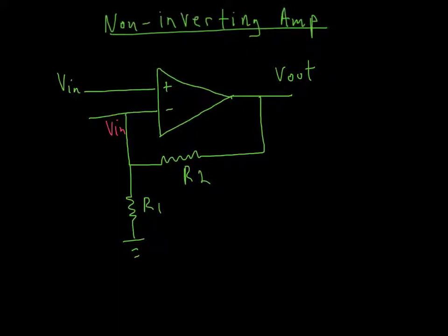Okay, and remember the op amp, golden rule number 2, the op amp draws no current. So if there's no current going into here, there's no current going back up into this junction. Can you see that it's just a backwards voltage divider, where if we were going this way, we go through R2 and then to ground. So this point here is V out. Let me label it down here, V out. This is V out. This point over here is Vin. No current goes up here. All the current goes through here. All the current goes like this. All right, and so look, that's just a voltage divider with our V out and our Vin flipped.